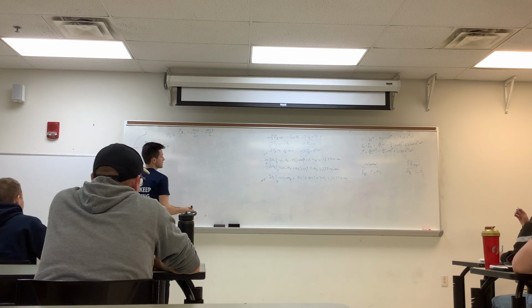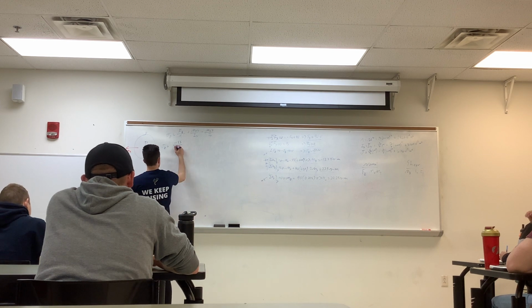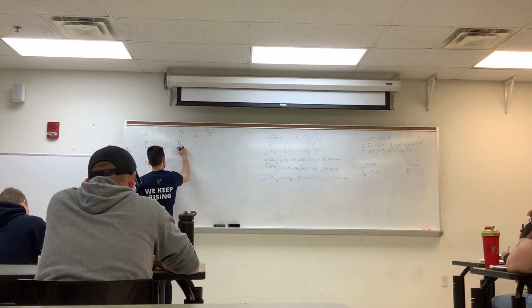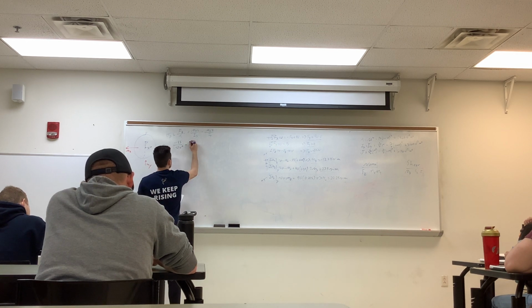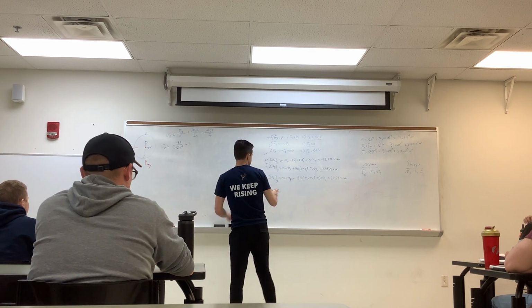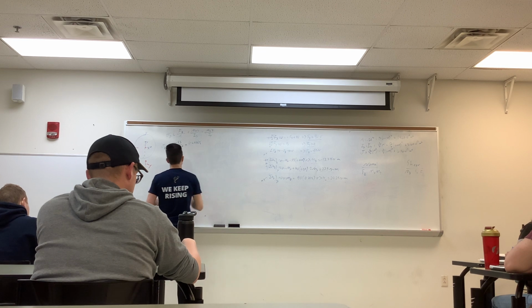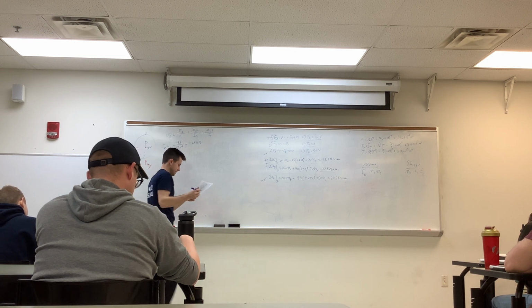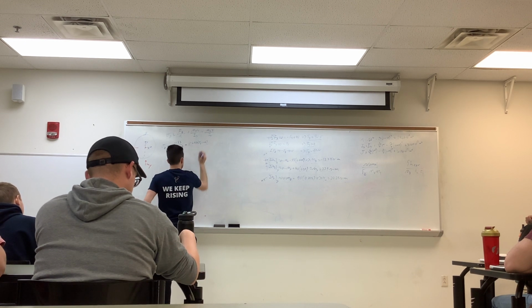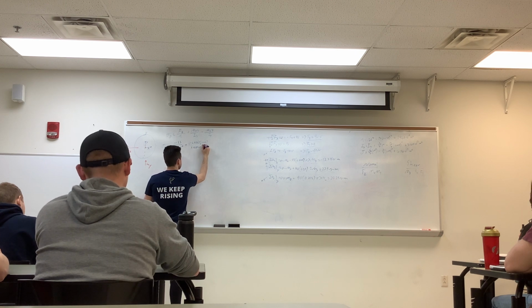We have our force in the z direction, which is negative 55 newtons, over A, which we got to be 1.963 times 10 to the negative third, plus the moment about x, which is negative 12.375, multiplied by that y distance from the centroid, which with regard to the x-axis is the radius to point H, so 0.025 meters, all over I, which is 3.068 times 10 to the negative 7th.